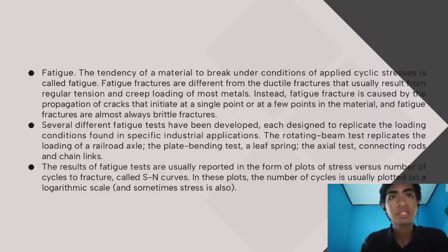The stress in a fatigue test usually is cycled between a maximum tensile stress and a minimum tensile stress, or between a maximum tension stress and a maximum compressive stress. The ratio of these extremes is called the stress ratio. The ratio for fully reversed stress then becomes -1. Other terms used to describe fatigue stress include mean stress, the stress range, and the stress amplitude.